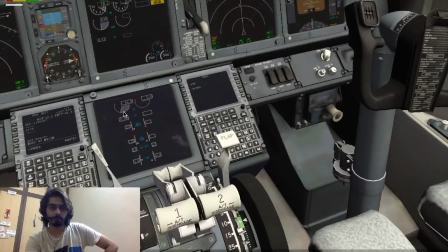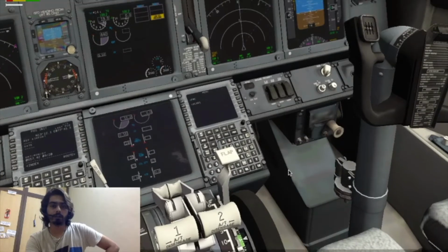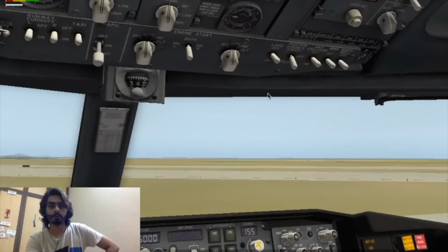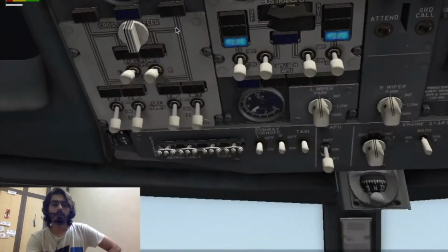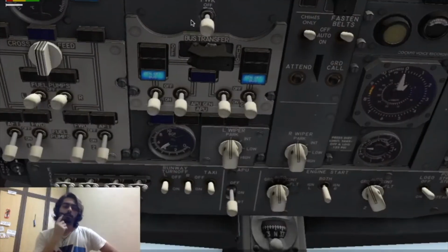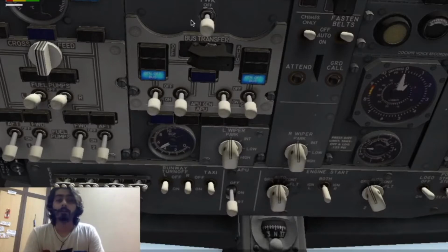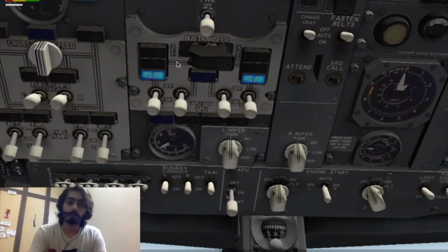So you see the left engine is now at good thrust, it's at good power, and the right will be starting off in a while because the right is not sent to ground, sorry, my bad. The right will start off now, and what we can actually do is, because the left engine has already started working and it is taking in air and pushing it back for thrust purposes, we can use that air to generate electricity, and that is what we will do. We'll switch on the left generator here.